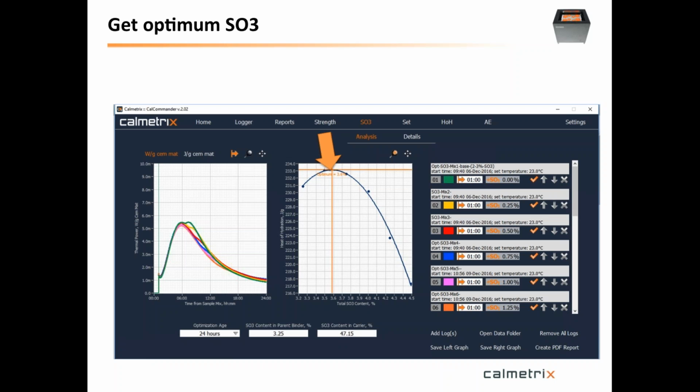But the problem with rheology testing, of course, is that it's not just slump. It's a little bit more complicated than just testing slump. And the rheometers that are out there now in the market are not necessarily very good for concrete testing. Actually, they're not good at all. What you find is either for paste testing or, at the very best, if you're lucky, you can test some mortar in there, but not concrete, or you find some that are good for field QC testing, portable rheometers that work somewhat for concrete, but they're not robust, they're not reproducible. It's not equipment that you would have in a QC testing lab.